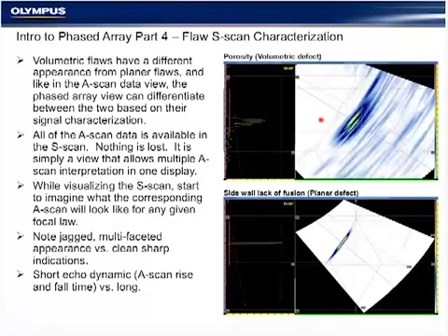And again, it would look very similar to a crack. The fact that it is embedded in the volume of the weld where porosity typically occurs is our key indicator on top of the A-scan indication. And again here, the location directly on the weld bevel, high amplitude, short echodynamic travel, or rise and fall time, is a classic indicator of sidewall lack of fusion.